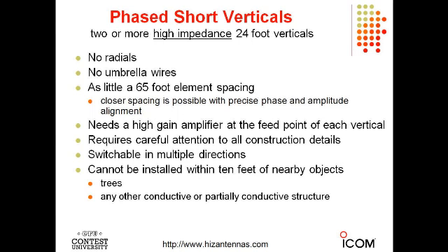So before you think about putting up a high Z array, it's important to think about where you're going to put it, so that each of the verticals is in an environment that's about the same, as close as you can to being in the same environment. You don't want to put up 4 high Z verticals with one sitting immediately next to a tree or one sitting immediately next to a building of some kind. It will disrupt the performance of the array.